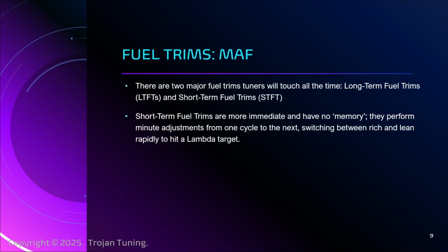They're just monitoring it, and they're noting whether or not it's rich or it's lean. And that qualitative, like, I'm rich, goes to the ECU. The ECU starts making adjustments based on this, and the fueling correction comes into play. Typically you'll see, if you're tight and tuned, STFT values of 2-3%.